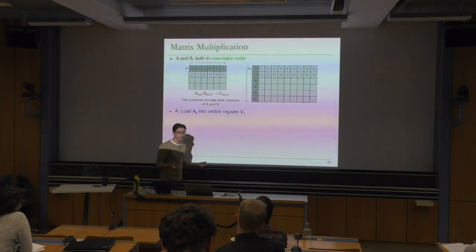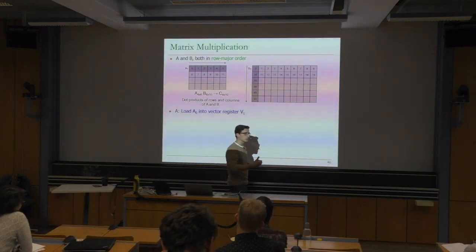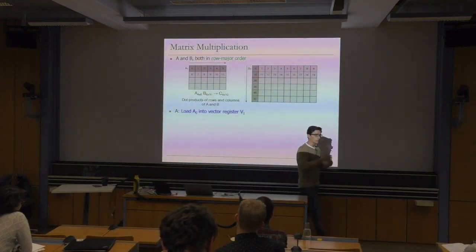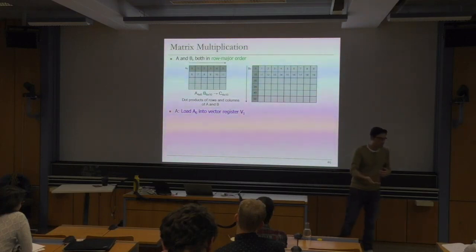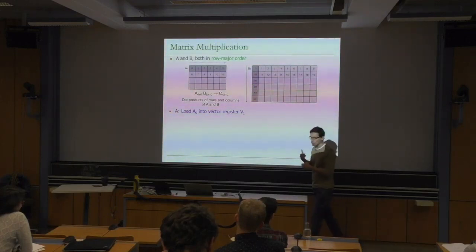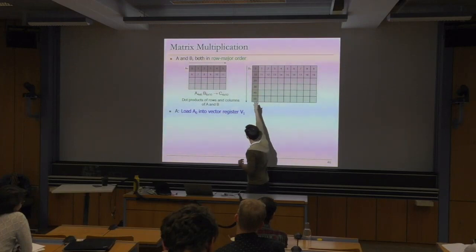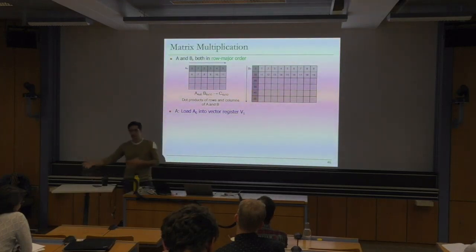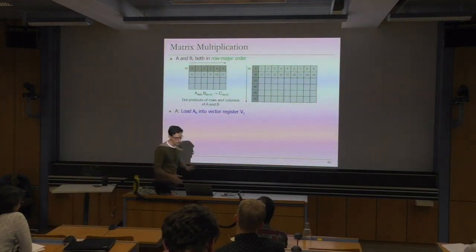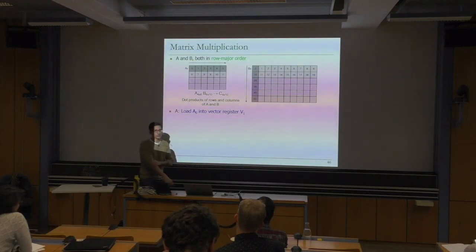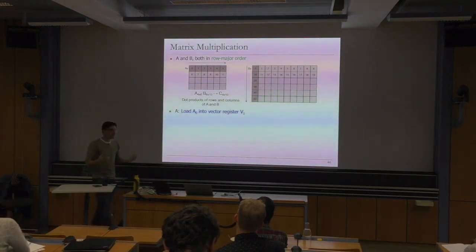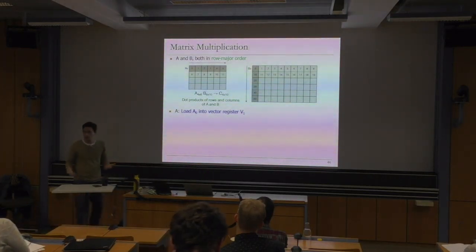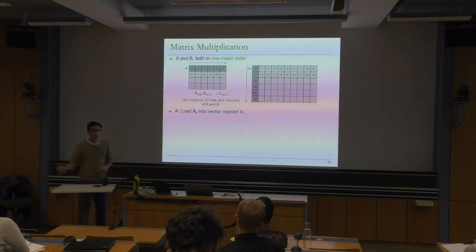And the problem with that is that we cannot perform the accesses in parallel, concurrently. But we will have to wait. In order to read B10, we will have to wait until the access to B0 is completely finished. Right? Are we always going to have this sort of problem? We will always have this problem as long as the stride and the number of banks are not relatively prime.